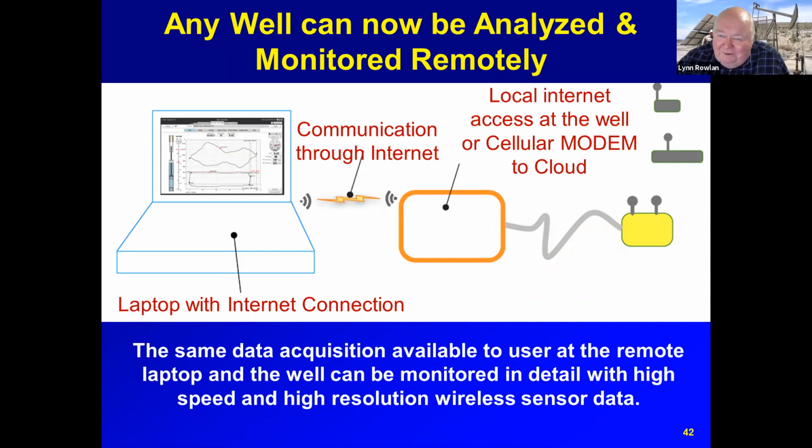And you need to have better information about the well, the deviation survey, because we want to adjust the pressure for vertical depth, not measured depth. The fluid level is measured depth. And we want to adjust the rod string weight for the vertical weight, not the weight of the whole rod string, because some of the weight of the rods is laying on the side of the tubing. So that's the answer. Yes, there's no problem at all. We do it all the time.